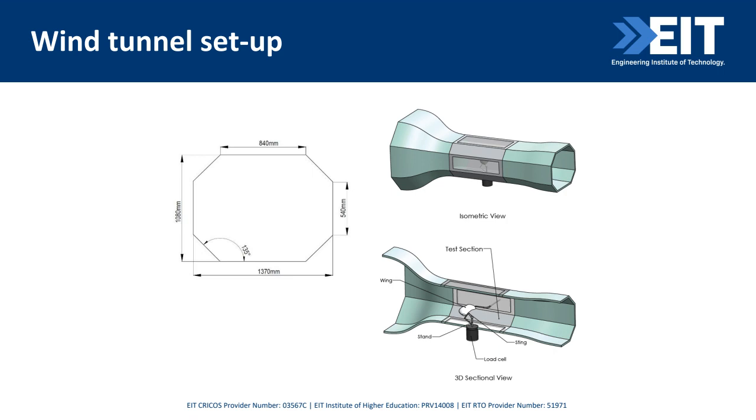So this is the interface for ANSYS Workbench that I used. There are three software already installed inside the Workbench, so you can use any of them. I like to use the new DesignModeler geometry, so just click on that. It takes a little bit of time to open. Then select the XY plane or any plane you like. I always select the XY plane, just to reduce the computational time.